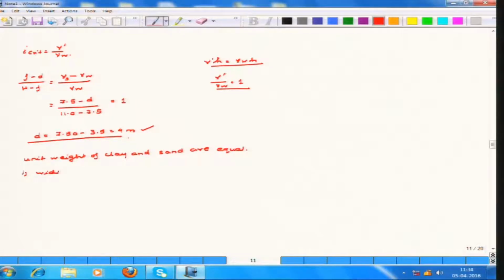the width of the excavation, in real life problems actually, is large enough, you can neglect the shear strength of clay, then basically it acts as a uniform load layer. Okay. But if the width of the excavation is small enough compared to the thickness of the clay layer, then you have to consider the shear strength of clay. In that respect, you have to consider both the critical conditions as well as the shear strength of the clay layer.